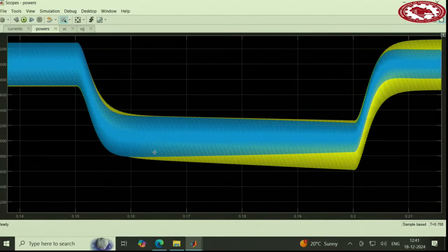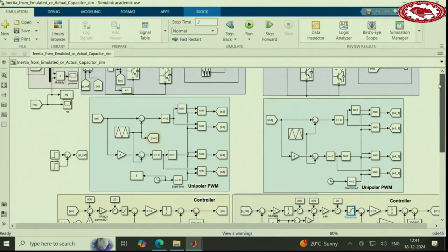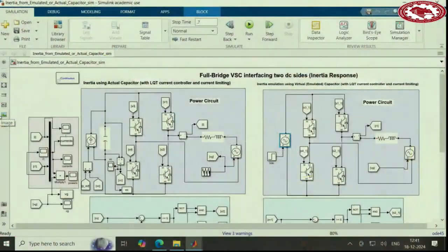Yeah, that's a very good question. I like this type of question. In the case that it's single stage, remember this is a battery here. In this one, it's a capacitor. So you either have an actual capacitor that provides the inertia or a battery that provides the inertia. So you should have a source. You emulate it, but you cannot create energy. This energy should come from somewhere. But our control makes sure that we create a very nice stabilizing inertia. But that energy should come from somewhere, from a capacitor or from a battery.